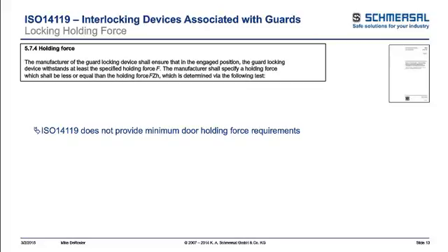The guard design has an impact. So, for example, if you have a switch that has 100 pounds of holding force versus a switch that has 200 pounds of holding force, what's the difference between the two? Because they're both locking, safety-rated types of devices. It might be in the design of the guard, where the guard design may warrant the 200-pound holding force because of the mechanical leverage that can be put on there, versus the 100 pounds of holding force, where the mechanical leverage may say that's not enough and we're going to force it open with very little effort by the operator. That doesn't mean that the lower switch doesn't have its application.